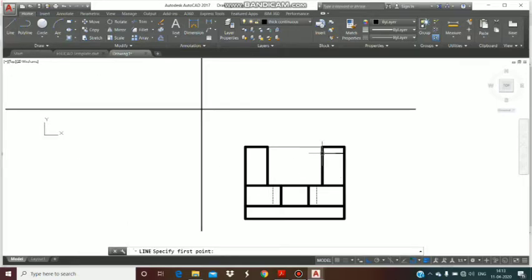From this it will be 25 because the diameter is 25. I have to show you at the distance of 25 up to this point. Similarly here on this side you have to draw a line of 12.5 and show a horizontal line here. Again a horizontal line at the distance of 25 from this end. These lines are hidden and thin.